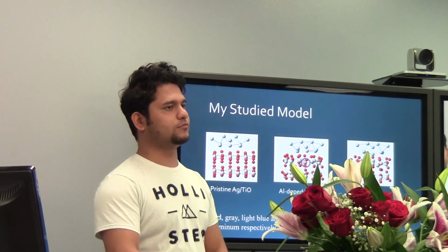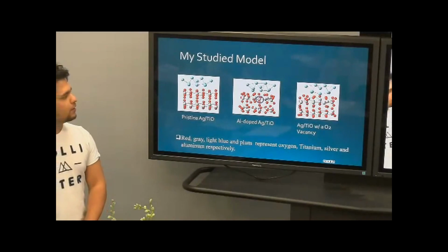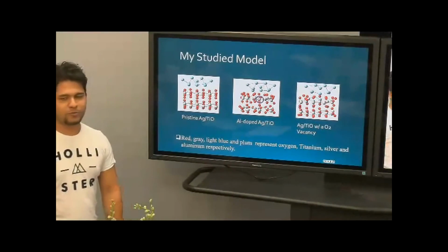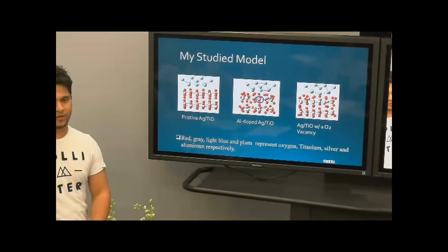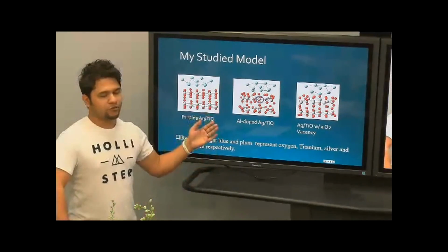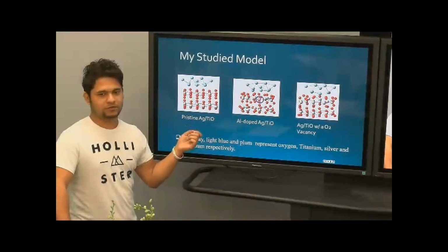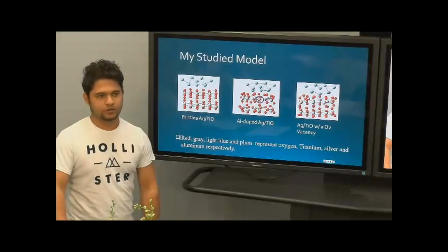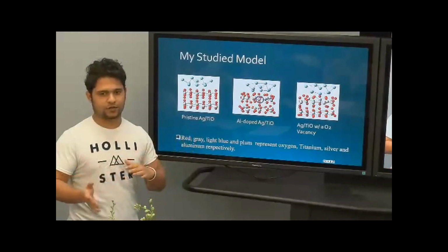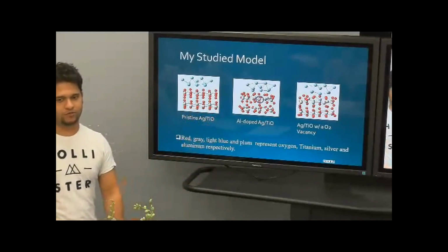Have you considered tunneling? Yeah, I have to. So I cannot make it much smaller. That's why I need to optimize. But is this big enough? I want to minimize tunneling because if I get more tunneling, it will become a conductor. So we need to optimize tunneling and the Schottky barrier too.